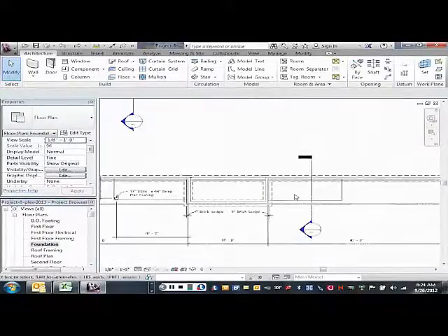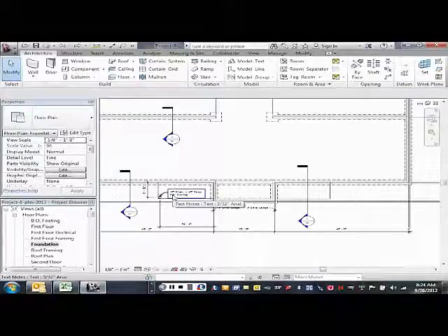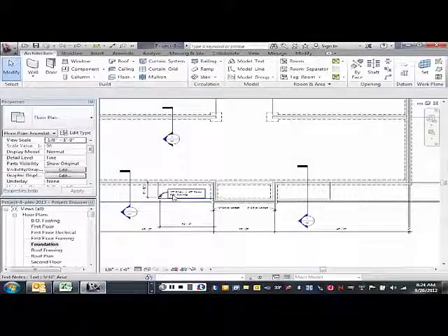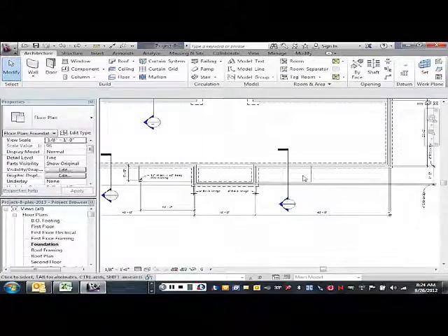I got my slab in there. Now I need to support that corner of the slab, because on the second floor we're going to have some decks coming out above this one, right? And those decks have to be supported by some columns. And so we need a pier footing under that.